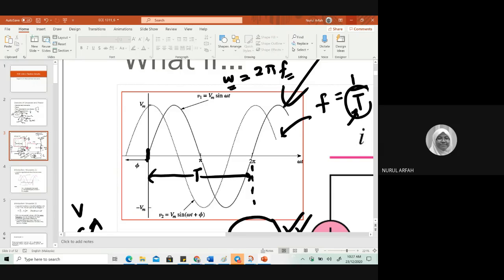But basically, what is T? T is when you have any sine wave or any pulse or triangular or something. As long as this is a signal, it will start from maybe somewhere like this. It starts from 0, and then will finish at also 0 like this. One cycle or one period of time, which is equal to 1 over f. Okay. All right. And this is a sine wave because it starts from 0. But if you have a cosine wave, it will start from here, and then it will finish up until here. Then same, frequency is equal to 1 over T, or T, the period, is equal to 1 over f.